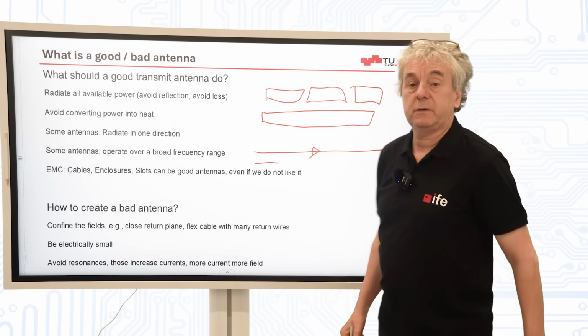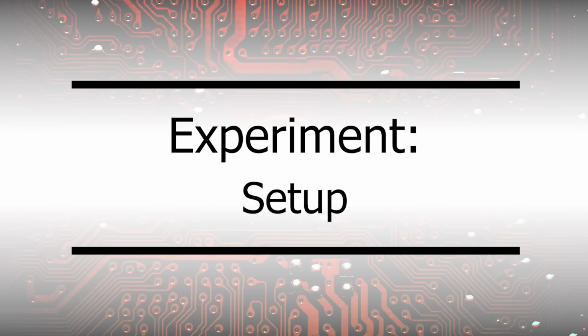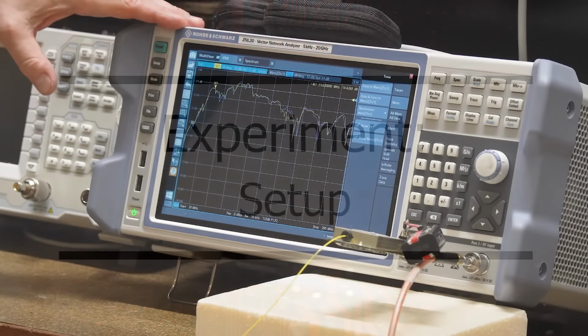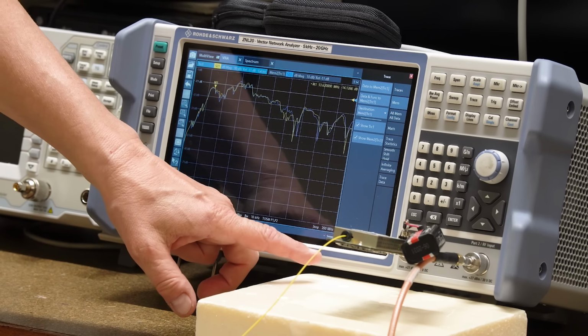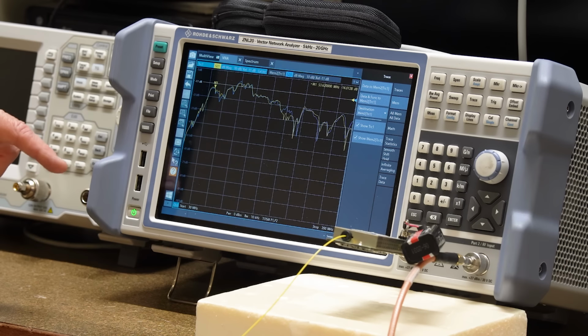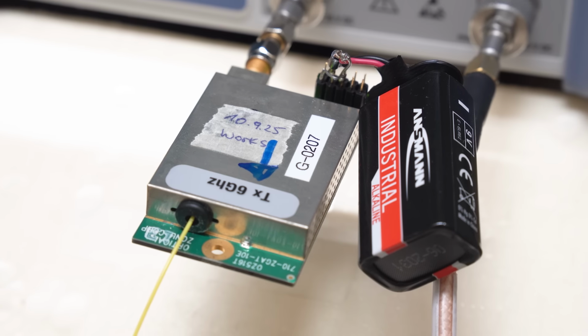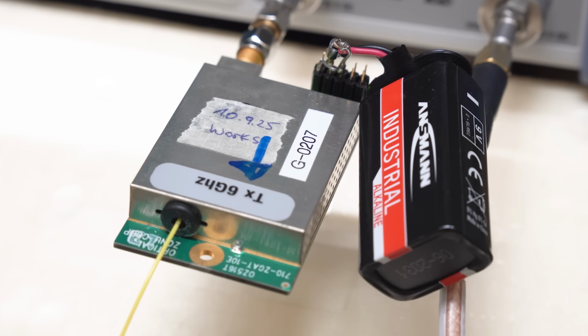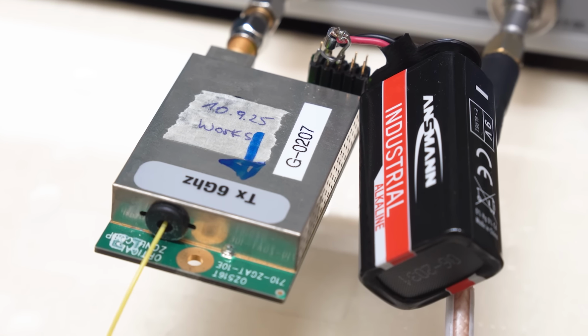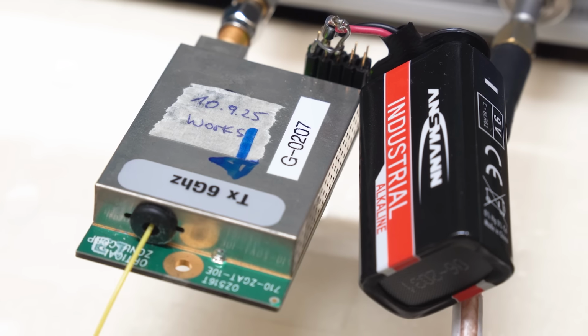Now, let's go back to the experiments. We have a setup. We have a network analyzer, and we go from 30 megahertz to 200 megahertz. And the output goes into an electro-optical link. This is the link from Optical Zonu, which we really like to use. It goes from low frequency to 6 gigahertz. We're only using 200 megahertz.